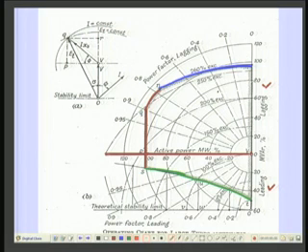The moment you operate within this, the generator will be regulating the terminal voltage, but the moment you reach the limiting condition, terminal voltage can no more be regulated, right.